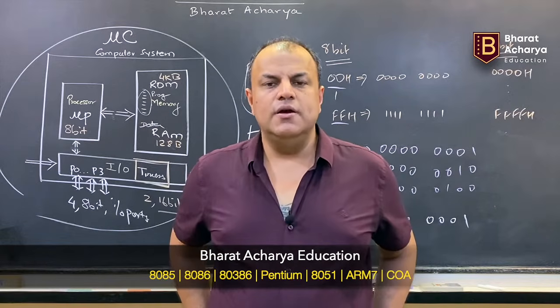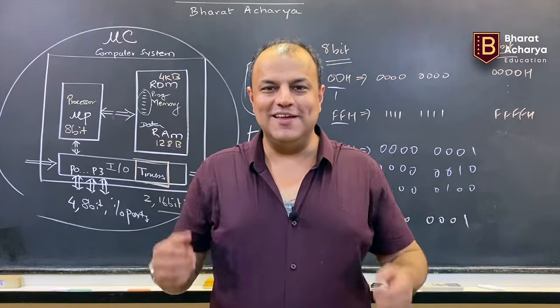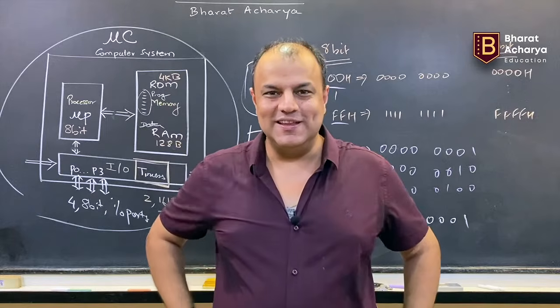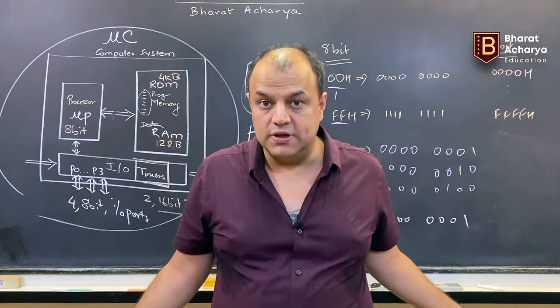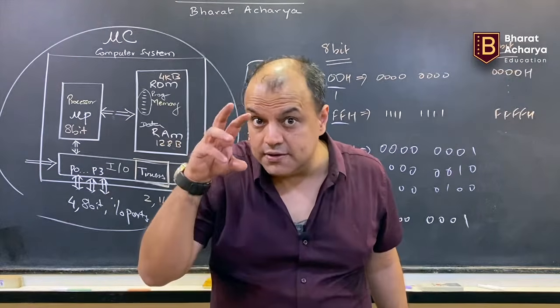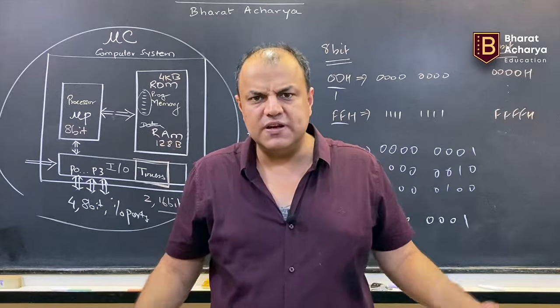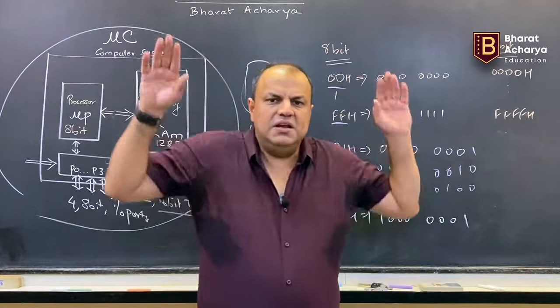So what's wrong with that? What's wrong is the processor was involved in producing the delay. So during the delay, the processor can do nothing else. This is okay for a traffic light because the processor has to do nothing else. Not in those lights where there's a counter. If there's a counter, the processor has to be free to display the counter. But most traffic lights don't have the counter, so the processor has to do nothing else. So over there, a software delay is fine.